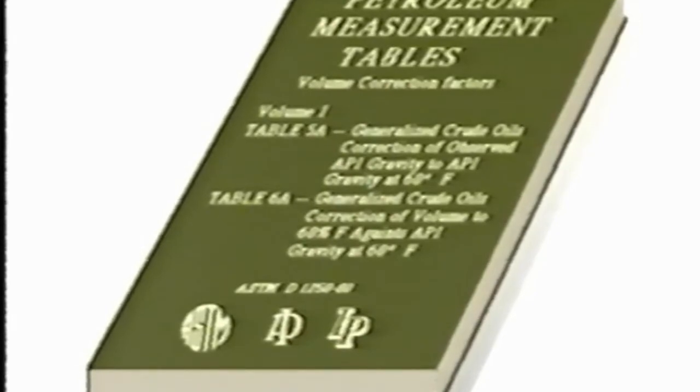To find the weight, reduce the volume to the corresponding volume at 60 degrees Fahrenheit. Use ASTM table 5A to convert measured API to corresponding API at 60 degrees Fahrenheit. A final point about using the MMC. It is bad practice to leave it unattended while fitted to the vapor control valve. The valve can close and damage a very expensive instrument.